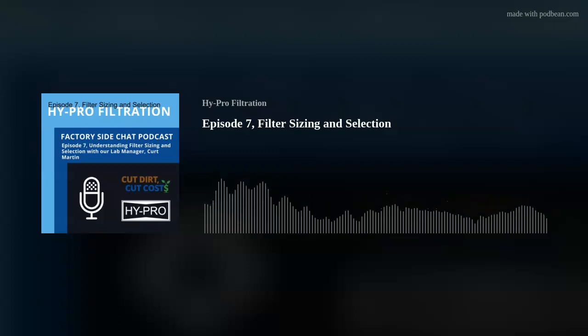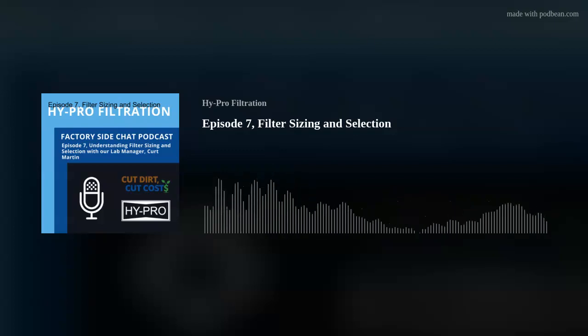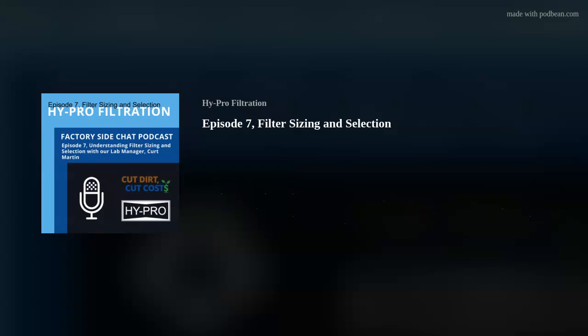So you've got to look at those conditions, factor in ingress rates, and then size the unit properly. Obviously, we'd want to size the dirty environments a little larger so that we get higher dirt holding capacities. We could keep up with the ingress rate, and not only keep up with it, but get ahead of it, versus a system that's in a really clean environment.